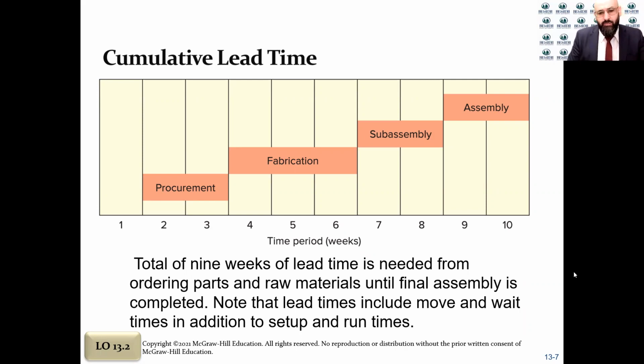Now we also have to consider some of the moving time and wait time in addition to the setup and run time. These are the other times that we should consider, not only the processing time. The lead time considers the move time, the wait time, the setup time, and the run time itself.